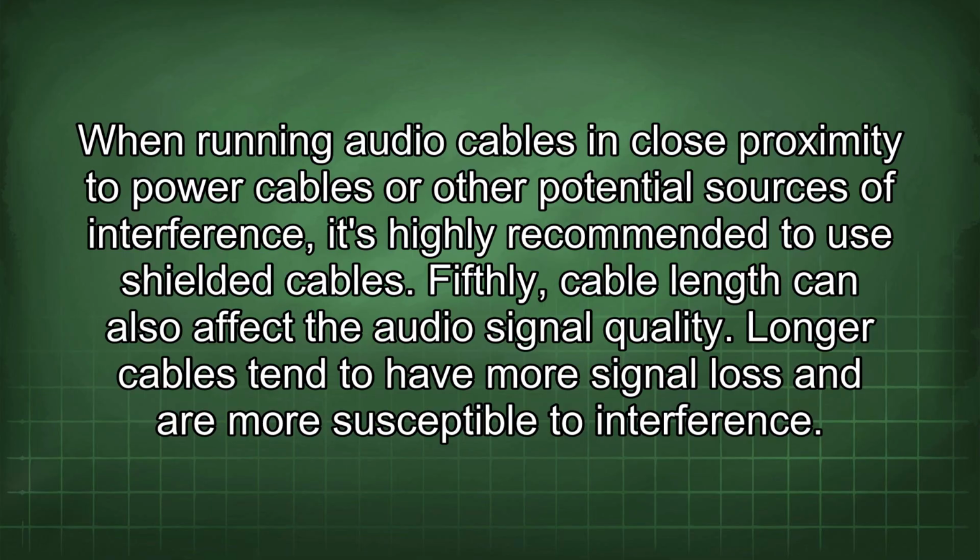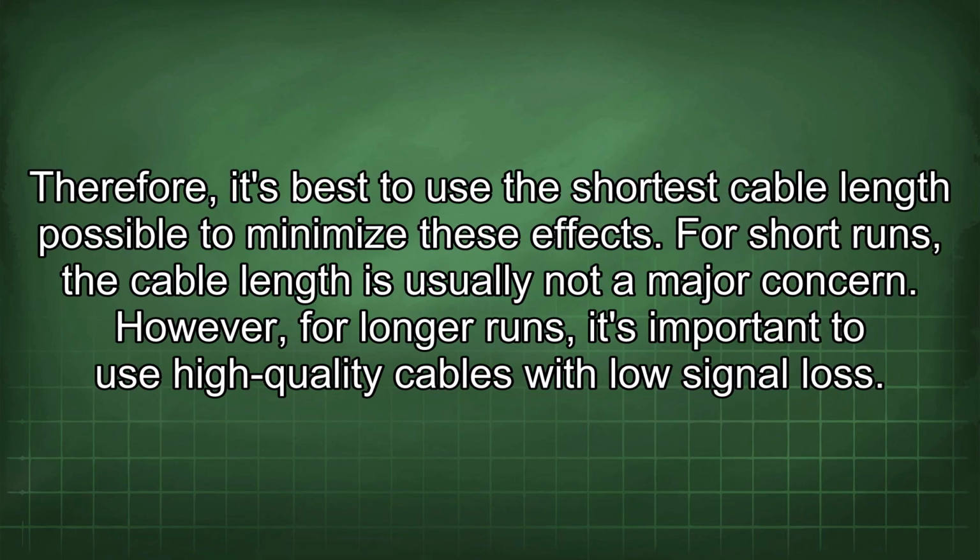When running audio cables in close proximity to power cables or other potential sources of interference, it's highly recommended to use shielded cables. Fifthly, cable length can also affect the audio signal quality. Longer cables tend to have more signal loss and are more susceptible to interference. Therefore, it's best to use the shortest cable length possible to minimize these effects.